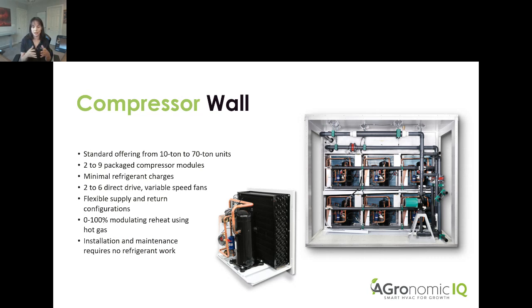So when you are on site or when installation is happening, all of your refrigerant is contained in these pods. And if you ever had a compressor go down, you could literally have somebody come out, pop out a pod, replace it with the next pod in about an hour and a half to 2 hours with 2 people, and you're back up and running.